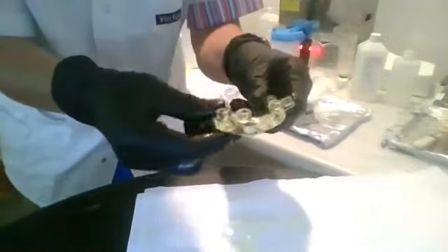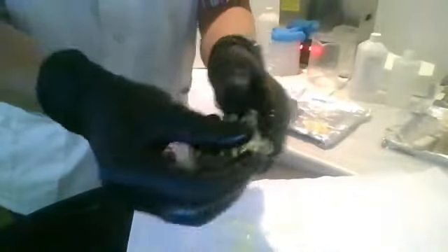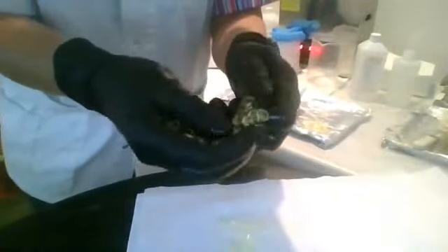Now the thing about it is, I want you to know that one of the tips I like to tell people is also to make sure you do this right away. You don't leave it sitting out in ambient light. I was sure to cover this with a napkin because I had a couple things to print for you today. Things will begin curing. So remove them from that build platform, rub off the supports, so this way they don't keep curing, okay? So even if you put them in alcohol with the full supports, they will begin curing and you will experience more scarring, okay?